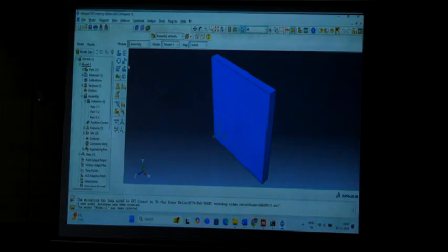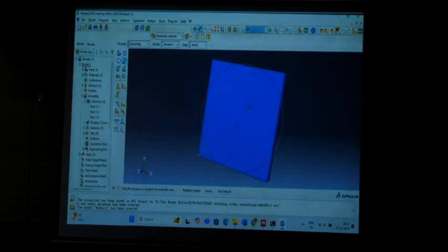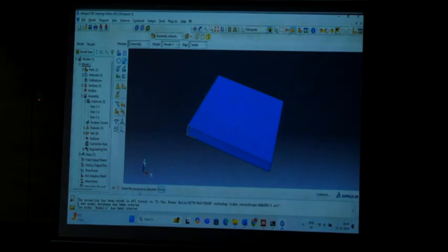Now in order to get all the things together, you just choose the option translate instance. If you can see here, the axis origin point XYZ, it will ask to select the instance to translate.